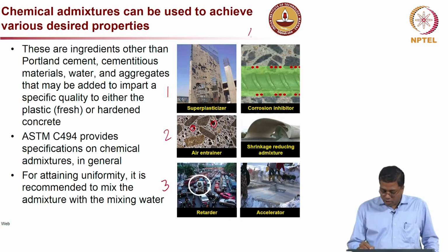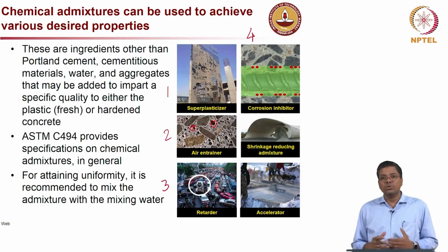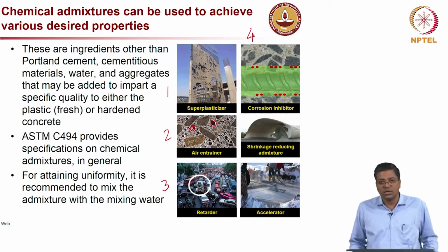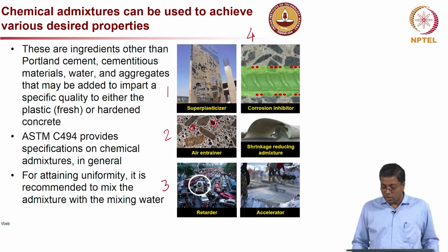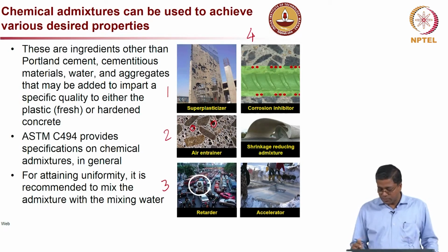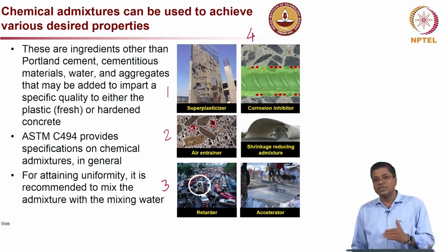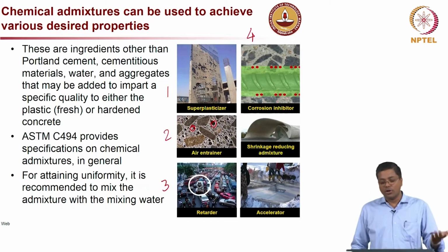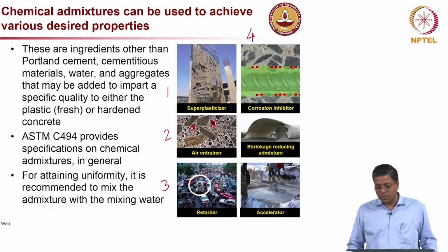Now, number 4 over here is the corrosion inhibitors, which are mainly used to enhance the corrosion resistance of the steel rebar or the steel concrete system. What it does, when mixed with concrete, is help in providing a better, more resistant passive film. My point to note here is, these inhibitors will come into action maybe after a decade or 2, depending on how corrosive the environment is.